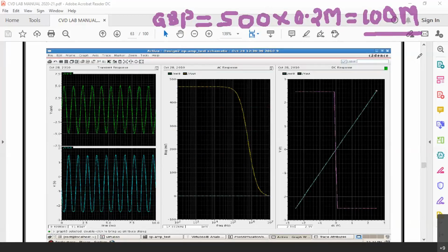Any guess? There is feedback. Okay. Feedback. No. With negative feedback, actually gain will reduce, bandwidth will increase, right? The feedback which we are giving through that capacitor is basically a negative feedback. So when we give a negative feedback, the advantage is that the gain will reduce and bandwidth will increase. It is not because of that feedback.